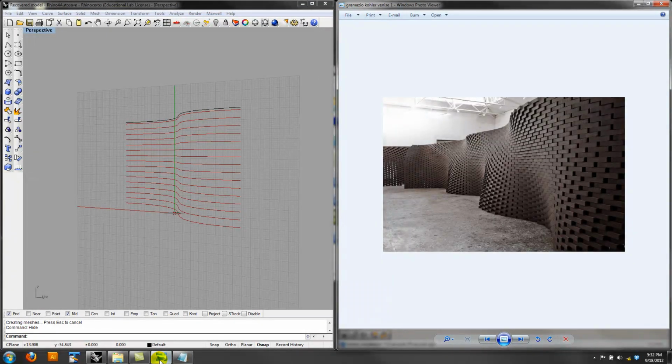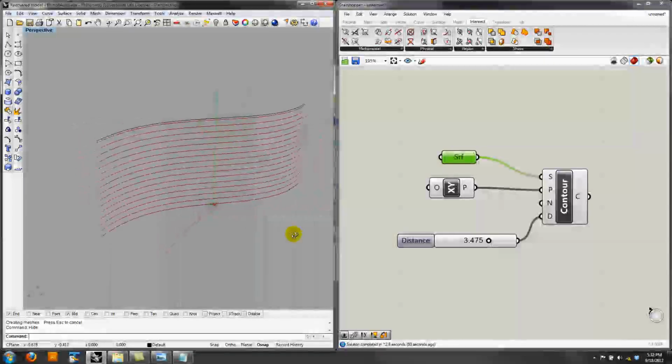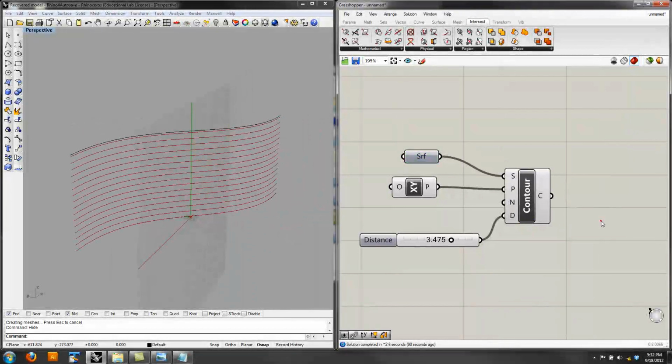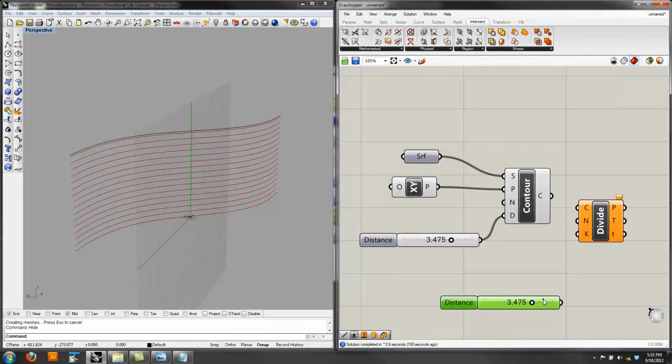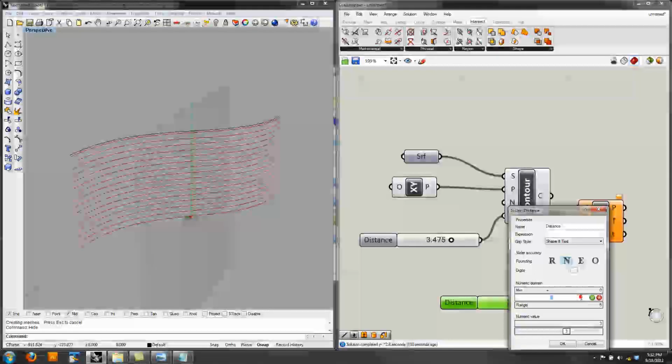Because we can see how each of these is kind of a band, there's a curve, and remember with things like divide curve or curve length, we can basically put points along a curve, and once you have points, you can distribute geometry, right? We can distribute things like our bricks. Okay, and so you could look at this and you'd say, well, I'm pretty far along here. I have this idea for this wall. Let's just put a divide curve in there. And we're going to need a lot of bricks.